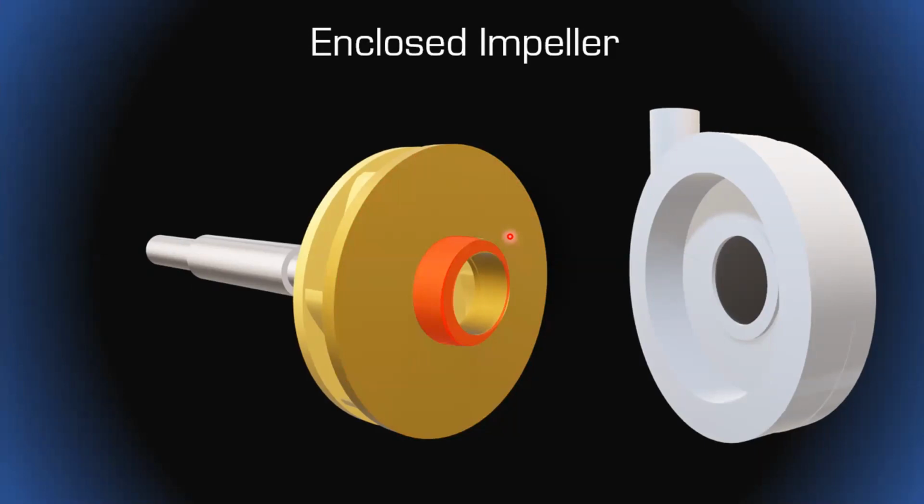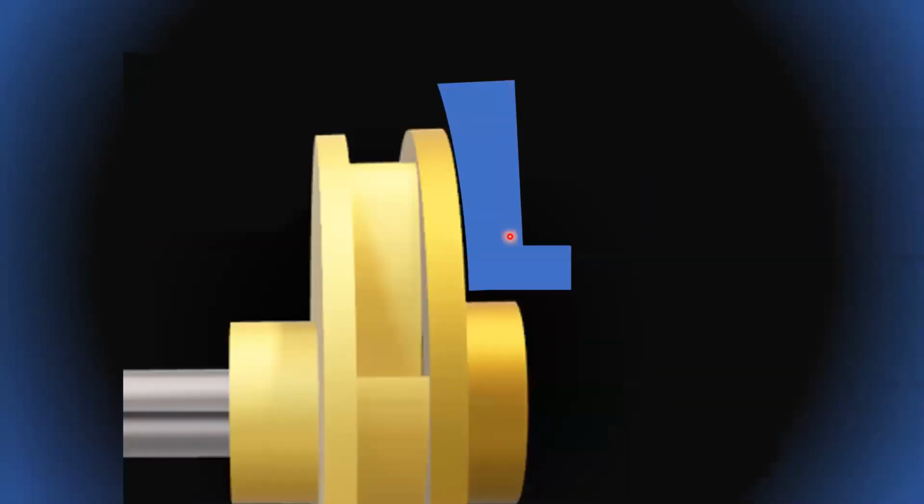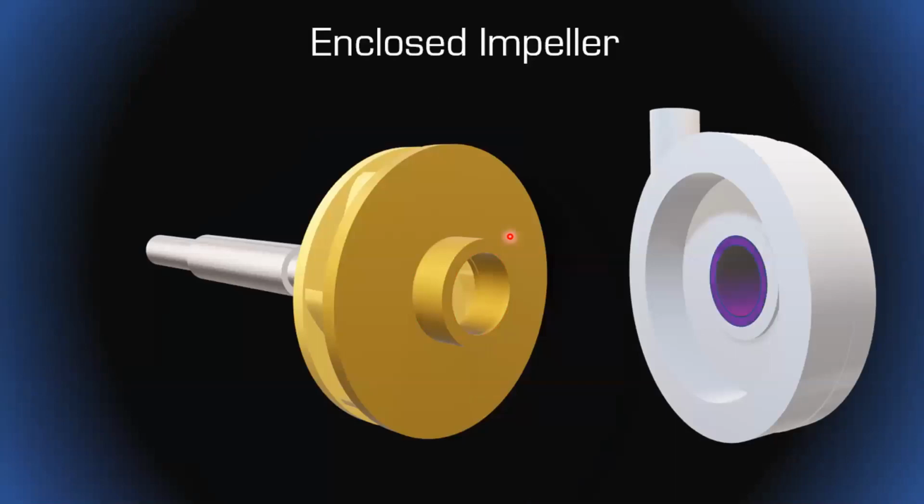And again, this is really applicable when we're pumping something that's not quite clean water, maybe something with a bit of silt or sand or slurry inside of it. So what we can do is insert what's called a replaceable wear ring, okay? And that's now going to be the sacrificial component that will wear instead of an expensive case. So let's take a look at where that would be. That would usually be pressed into the volute itself. It's just a press fit.